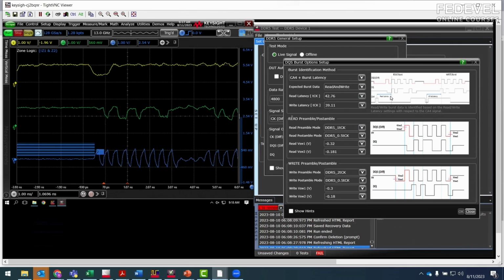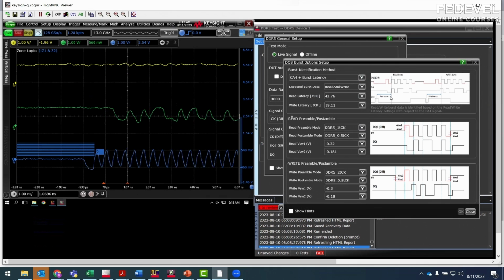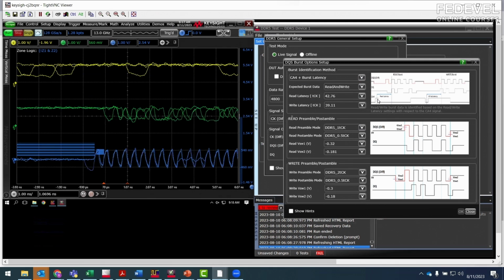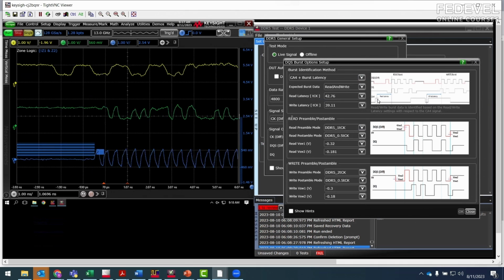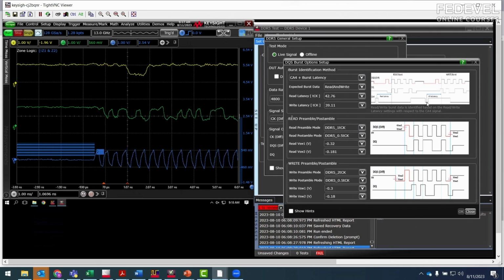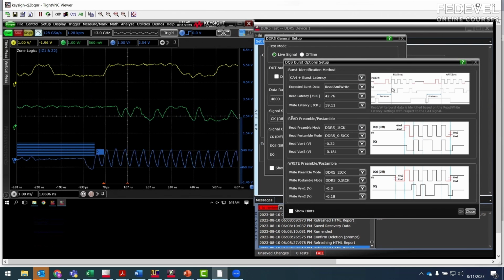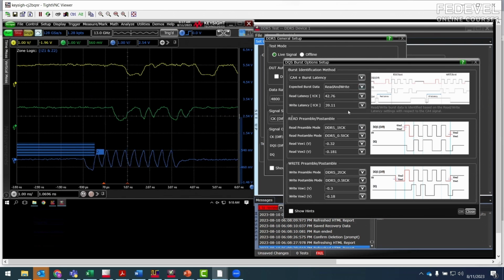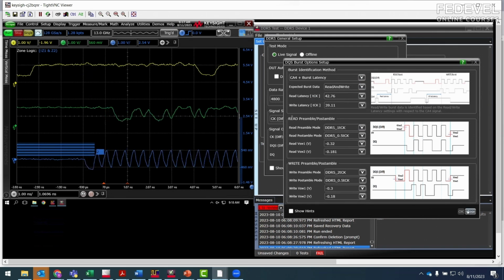Now, in reality, there are commands that may not correspond. Maybe the CA4 is high because it's in an idle state, because the CA4 is pulled up to high. That's the normal bias termination voltage. But for sure, we can predict that if the CA4 is low, it's a write. So if it's not a write, we assume that the burst is a read. Anyway, we have to put in these values. And so that's one part.